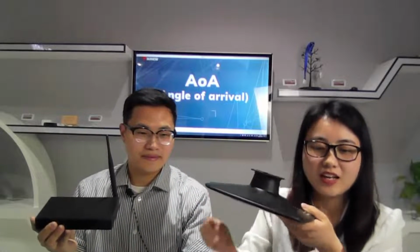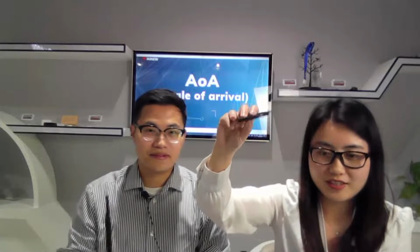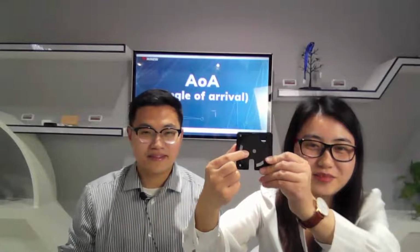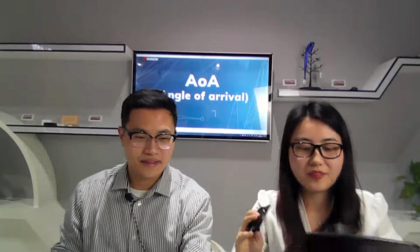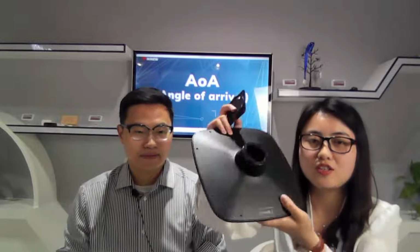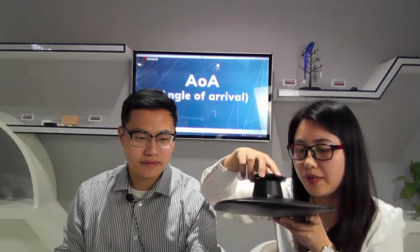I will show you. This is a locator base. We will fix it on the ceiling with screws. Here is the place to put screws on the ceiling. And here is a cable interface. We put the cable connector with the G2 gateway. So after we input the cable, we will rotate the locator and base together.